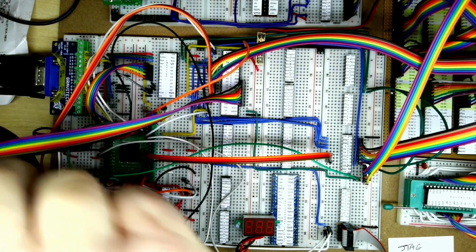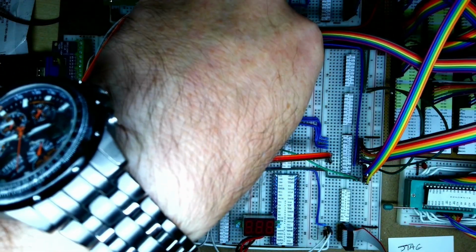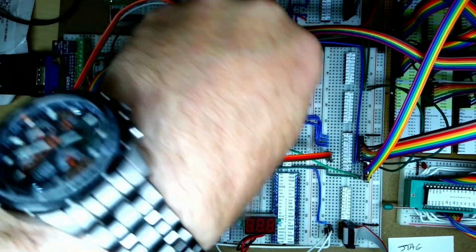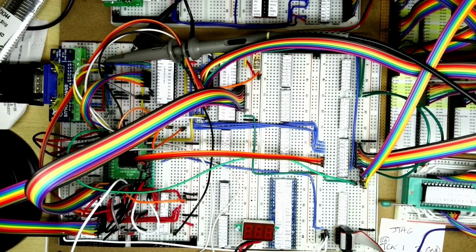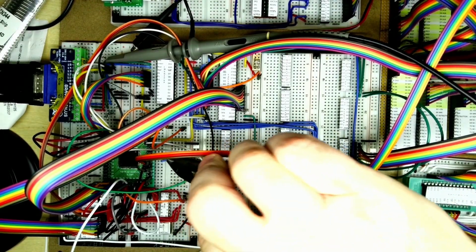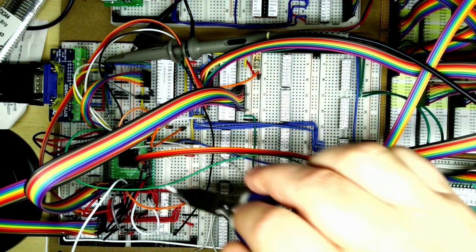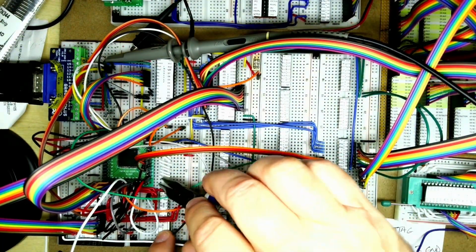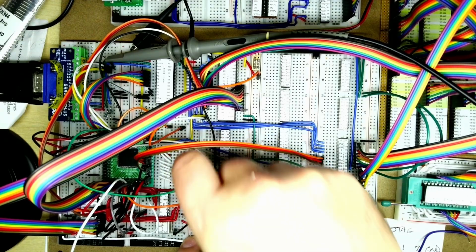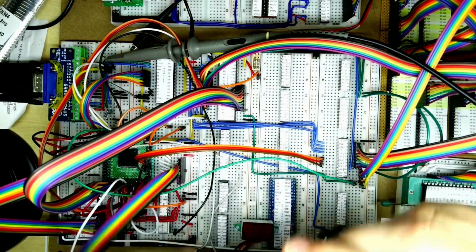Okay, so that's the video data hooked up there. So I'm just going to hook those up to the same address lines. There we go. So just need to do the data bus. I'm just going to pull this one out from the programming leads, and there's the data table, pin one down the bottom, and we just need to put this over to the data bus over here.